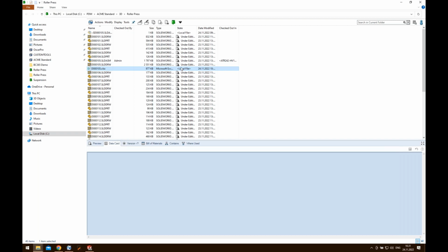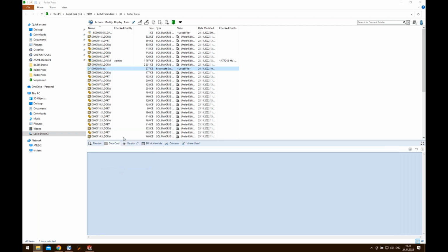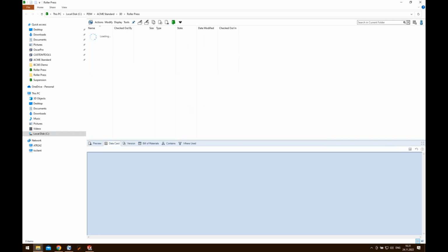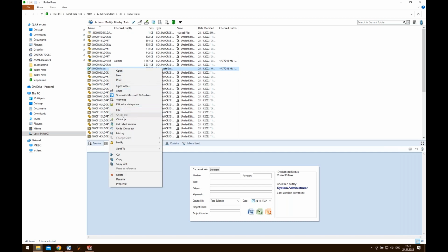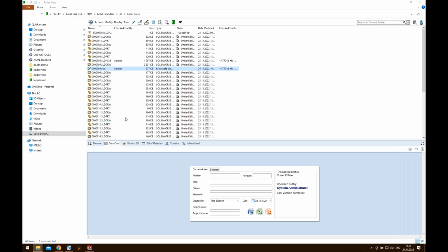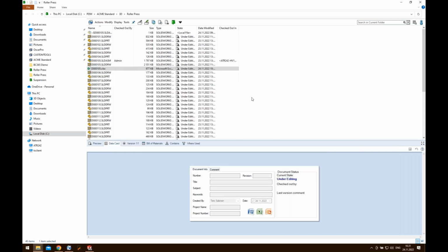So if I'm not aware of this, no one else can see my Excel file. So what I need to do is right click and add file to vault. So after this, it's part of the PDM vault, but still in order to allow others to use my Excel file, I need to check it in. So this is something that when working with the PDM Standard, you need to do manually.